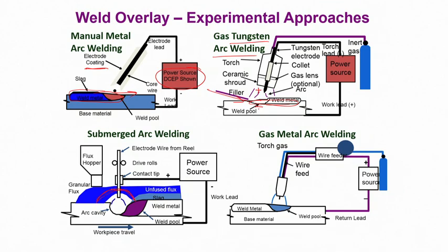So this is a solid flux material, powders or some kind of thin layer, and the composition of this flux is such that it reacts with the metal and creates a slag phase, an oxide phase, which is not going to dissolve or be part of the weld zone, but this region is the material that you have fused or welded. So this welded part now fuses well and becomes a part of the substrate.